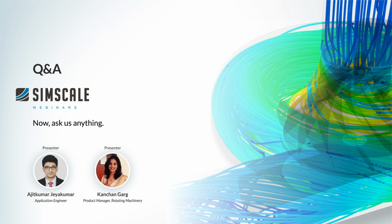The best practice here from our side will be if you have a narrow channel, make sure there are at least 3 cells across the thickness of the channel. And if you're refining the rotating zone, make sure between each blade, the gap should be refined starting with like 10 cells. And then if you want to achieve higher accuracy, you can go more or go less according to your requirements.